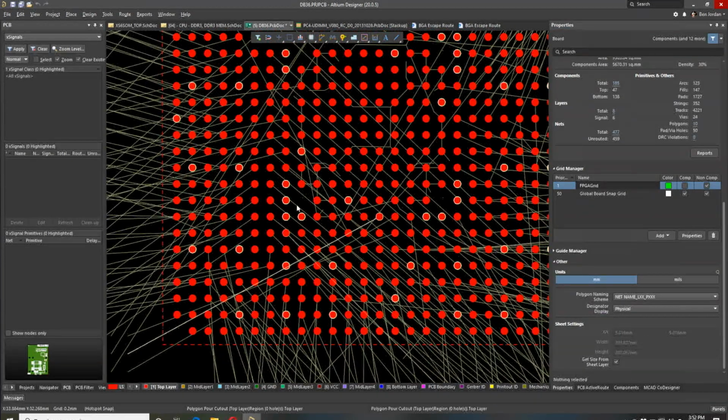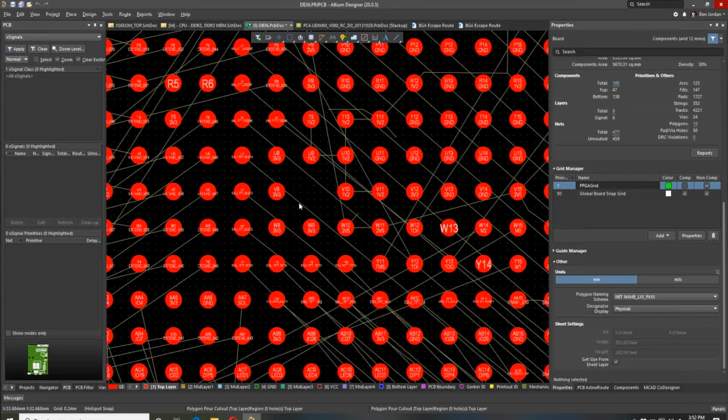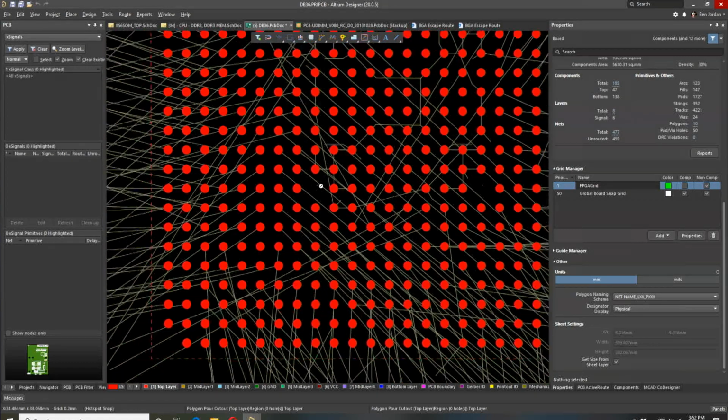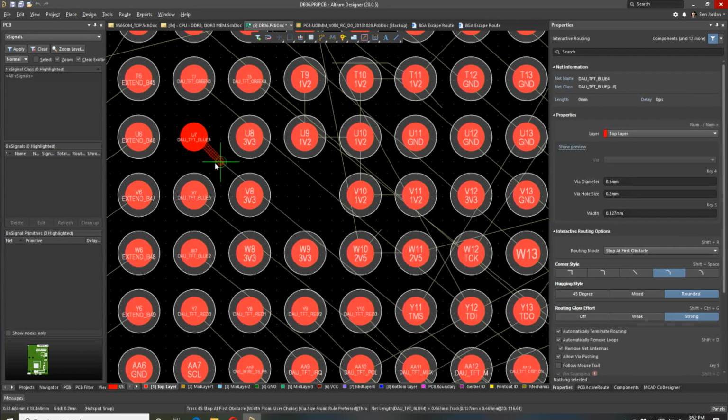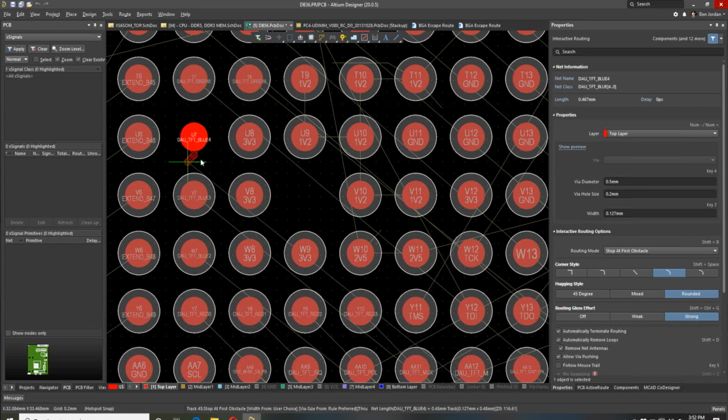you can see these are my fine dots. It's probably really hard to see on the projector screen there. And those are a nice multiple of the spacing between these BGA pads. So I can easily go anywhere I want. And of course, I've got AD20 beta running now, so you can see it snaking around there at any angle, like Chris was doing earlier.